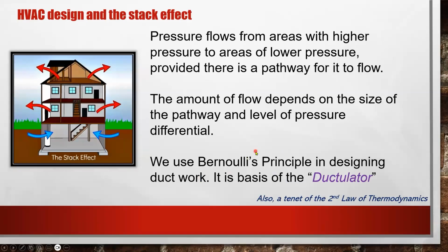Pressure flows from areas of higher pressure to areas of lower pressure, provided there is a pathway for it to flow. And the amount of that flow depends on the size of the pathway and the level of pressure differential. And we use Bernoulli's principle in designing ductwork. It is the basis of the ductulator.